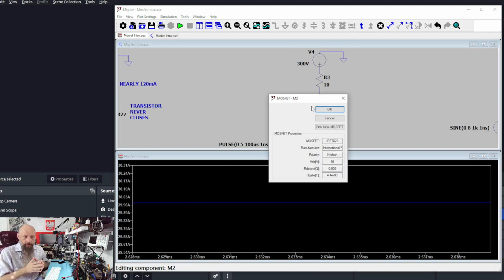Well, by perfect, I mean almost perfect, because one thing that we didn't have on our bipolar transistor, and I said that this parameter is not relevant, that's why it's not usually displayed on the data sheet, is the resistance between collector and emitter. In this case, resistance between drain and source, we can see that it's 5 milliohms. In MOSFETs, that is important because MOSFETs are going to be driving loads, while the bipolar transistors usually not, and if they do drive loads, these are small loads, not a lot of current going through.